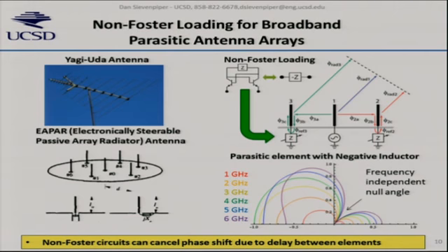The problem with these is if you look at where the radiation's going, that driven element radiates directly. All of the passive elements, the radiation has to hop over to that element, down the feed, off of that reactance, which you're tuning, come back up and reflect back or transmit back out. And sure, that can add in phase to produce some desired beam at exactly one frequency. But how could those paths possibly add up at all frequencies over a broad bandwidth?